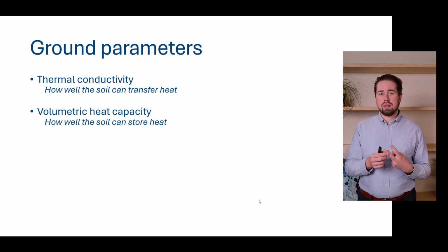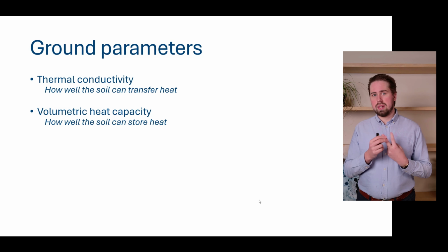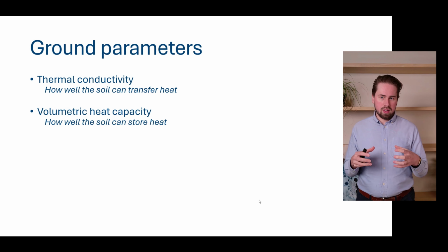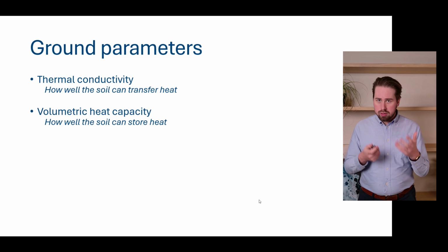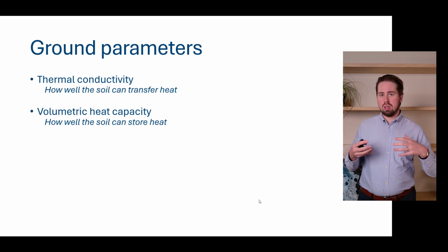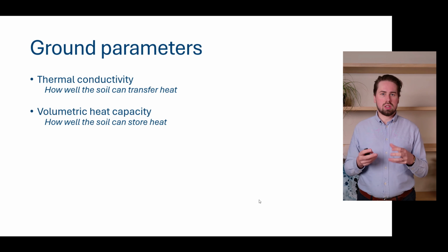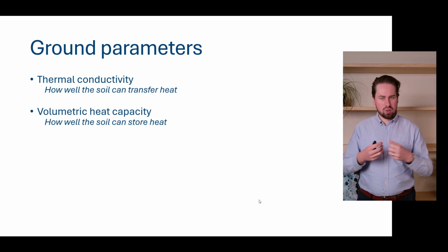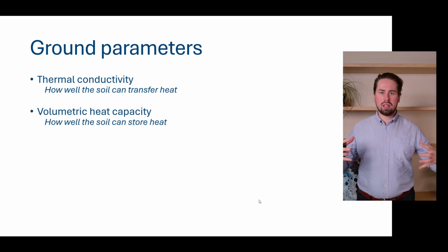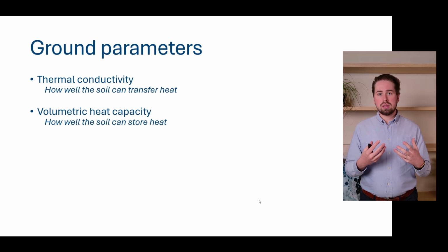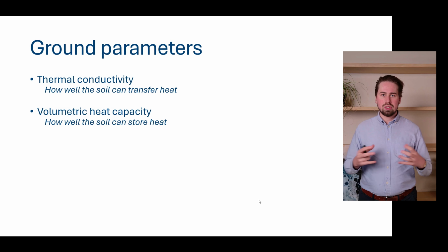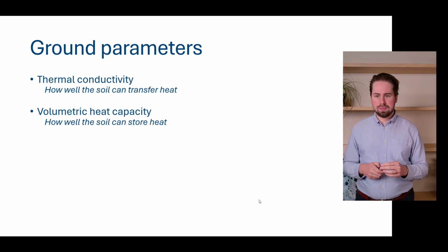The other important element is the ground volumetric heat capacity. That's a measure of how well the Earth can store energy. We already talked about bore fields as seasonal thermal energy storages. Well, that has to do with this ground volumetric heat capacity. If the ground can store quite a lot of energy, then the bore fields you install in this ground will also have good seasonal thermal storage.